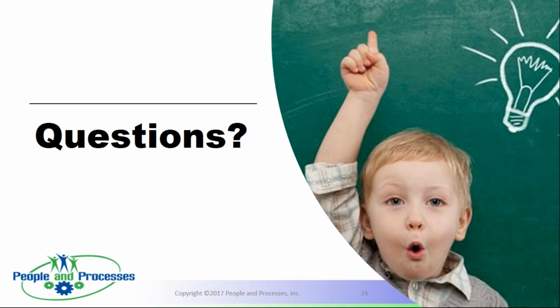So if we're not doing it well, if our PM tasks don't add value, then what happens is we tend to be really reactive. And so, if we've got a high PM compliance, and yet we're still having a lot of failures, then that points to maybe you need to get people into the RCM2 introductory class so they can understand how equipment fails and how to better write those tasks, because simply, the PM program's not doing what you expect. And I'll share with you too, what we found from RCM2 analysis is that as much as 40 to 60% of the PM tasks don't address any of the likely failure modes of the asset.